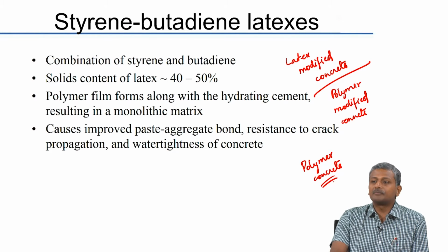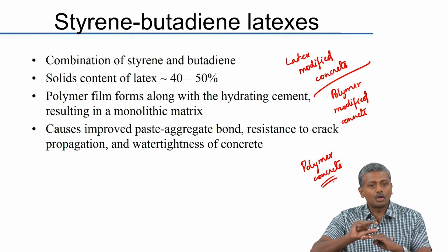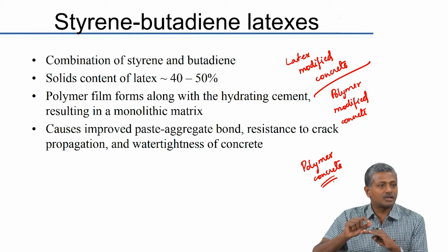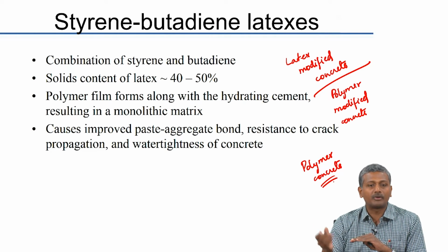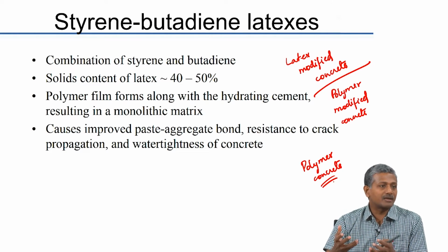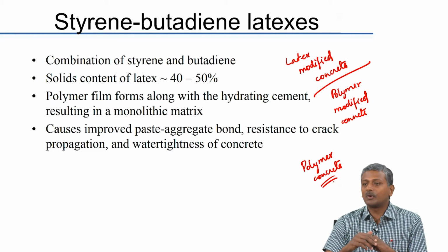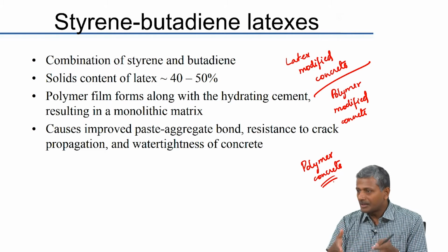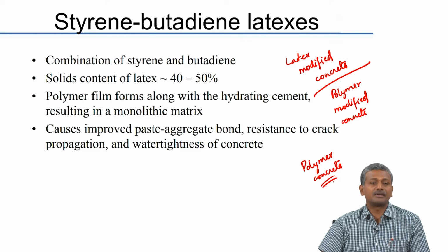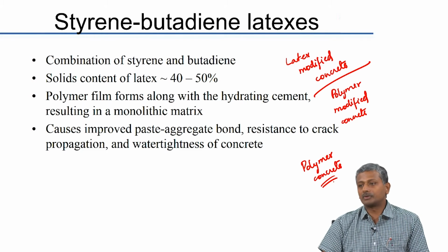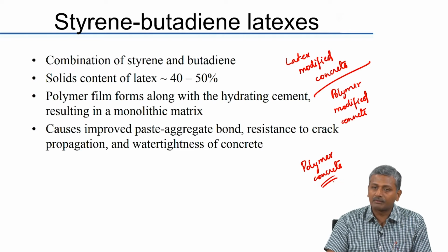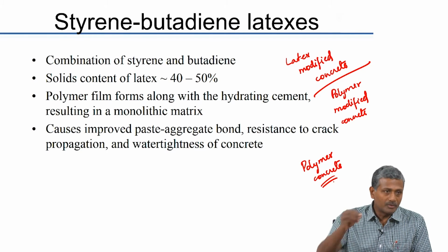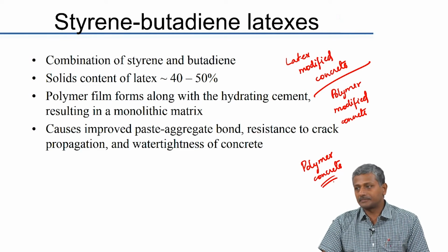You have seen that there are some flooring systems that are put on top of regular flooring systems to provide extra degree of stability and hardness of the floor. And these floorings are typically not done with cement, they are done with some material called epoxy. So, epoxy is mixed with aggregate and simply laid on the surface, which provides a very high degree of resistance to damage because of falling objects and accidental hits and so on. So, polymer concrete is where no cement is there, but polymer modified concrete is regular concrete where polymer has been used as an ingredient in the system.